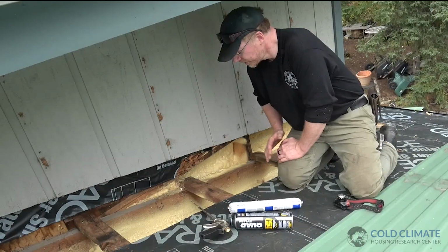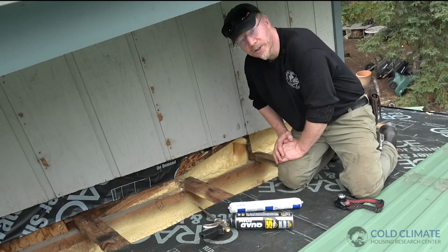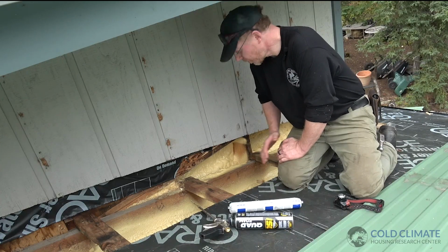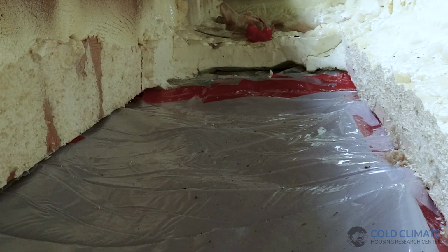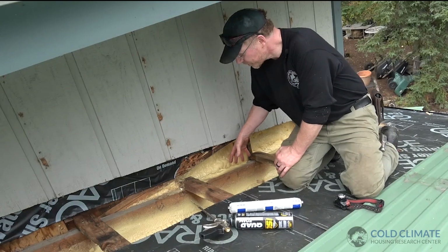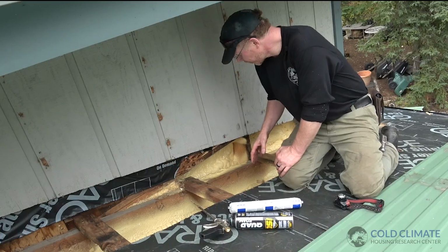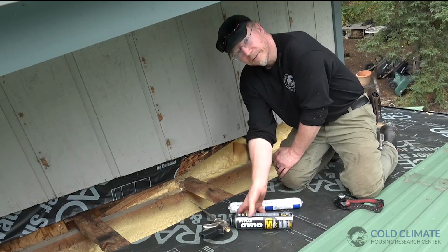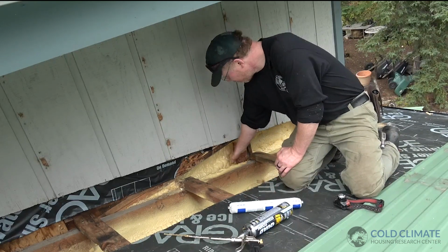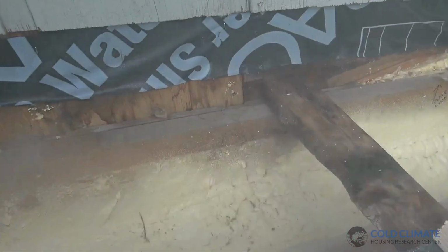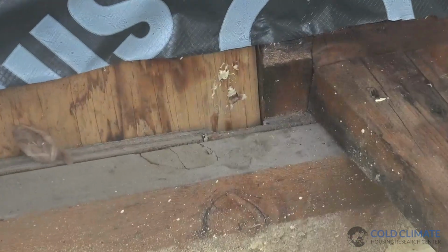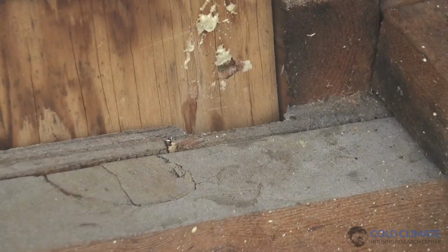Our fixes to air seal all the holes we found during the smoke test, those are pretty straightforward with one exception. To start with, we're going to patch this large hole we cut into the foam with foam board and more spray foam. But as far as all of the actual air leakage points themselves, most of them we can fix by injecting more minimal expanding foam into the holes or places where there's channels on the backside in these stud bays that we could feel and see were open and the smoke came out. We can inject foam into there.